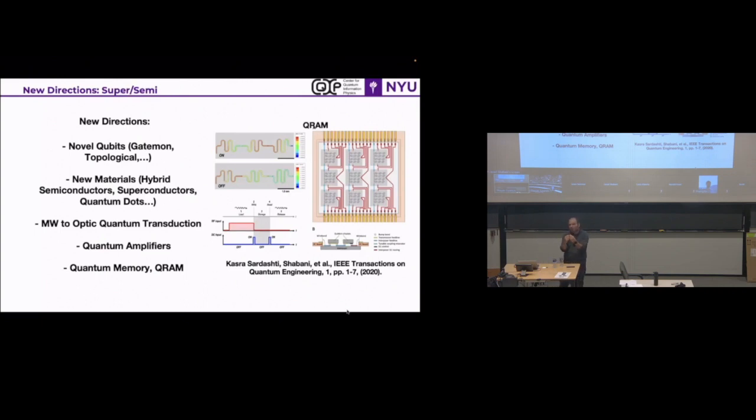But when I want to do a computation, I actually need the photon. So I can't just wait for seconds for this atom to come. If I have a switch that basically takes the mirror away and the photon comes out, now I can read it out with a readout signal. So basically I send an RF, I send a DC line. The moment that I turn this on, the photon comes out because it shorts the resonator out. I can get a swap operation with my bus line, then I will cut it down, right? So if you have a switch in superconducting circuits, it can actually take you a long way.